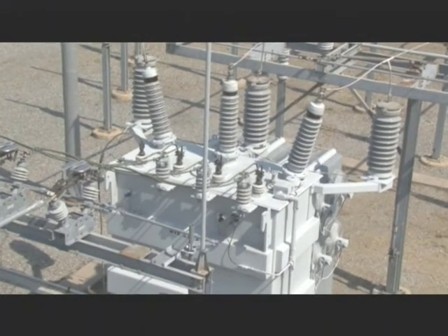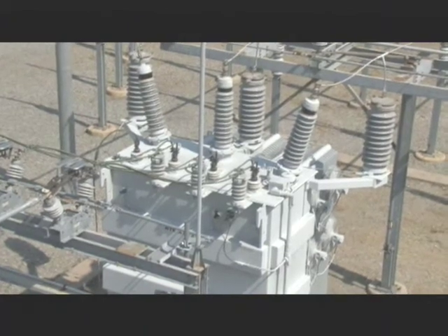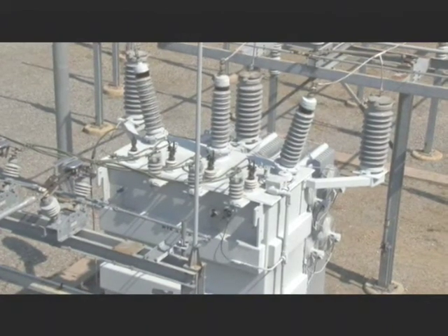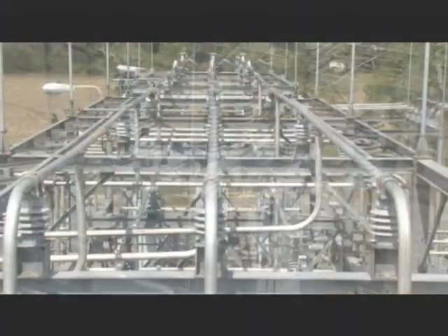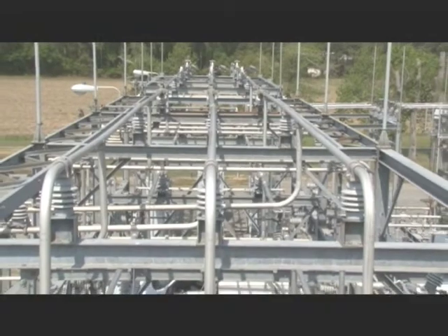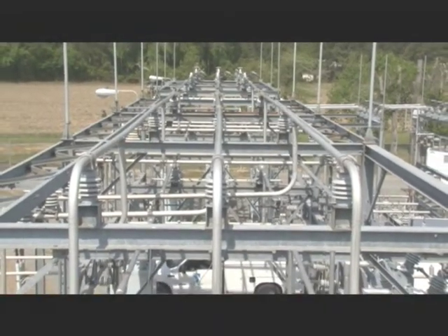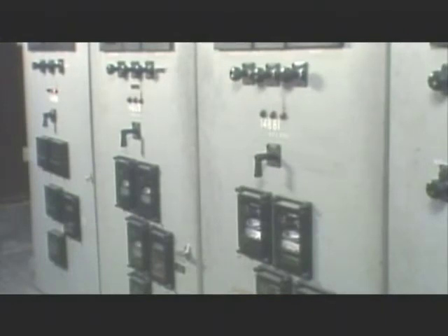As you'll recall from the last part of this program, transmission lines supply a substation with electricity. The transmission voltage is changed to distribution voltage by substation transformers that supply electricity to a substation bus. The substation bus then supplies electricity at primary distribution voltage to feeders. In many systems, circuit breakers are installed between the substation bus and the individual feeders. Generally, there is one circuit breaker for each feeder.